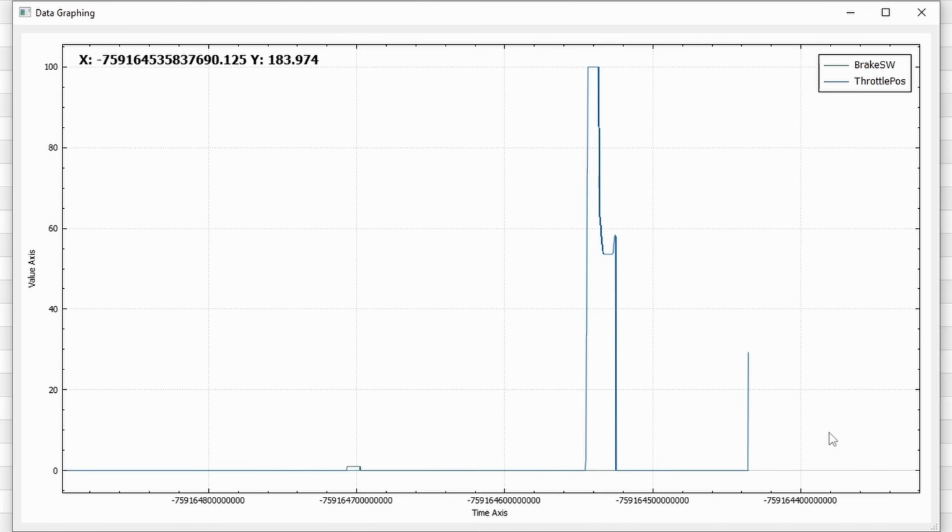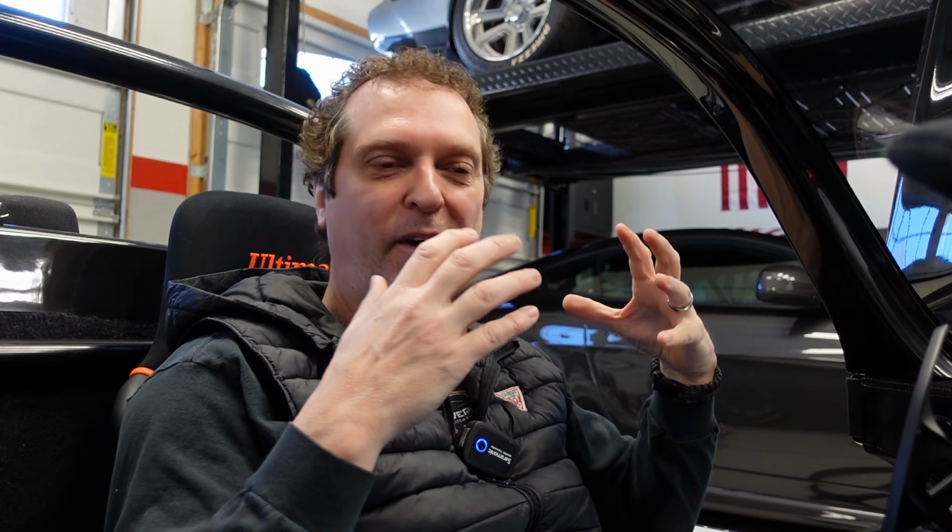So I'm going to go throttle, partial throttle, kind of hold it. We're up around, what, 40% throttle or so. Give it some more gas, hold it a little bit. See, we're up around 50. Now I'm going to get off the gas completely. Off the gas. Boom. So now we have the right scale, 0 to 100. Okay? So that's how we identify these basic CAN IDs that we're looking for.